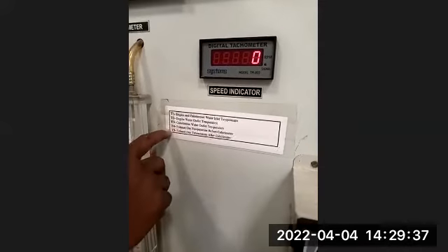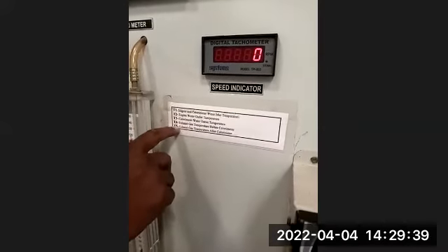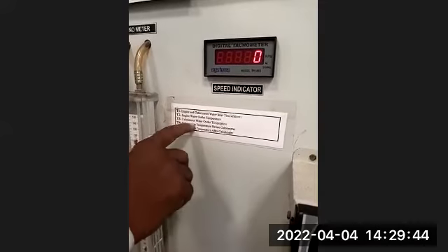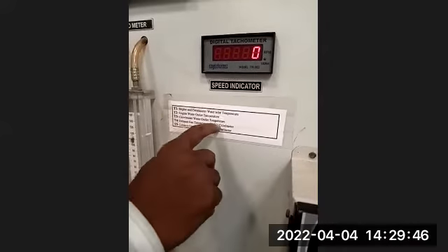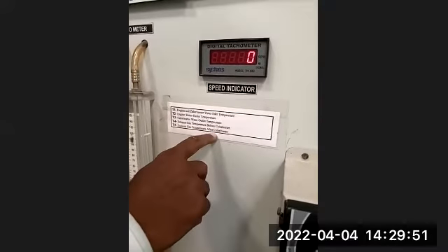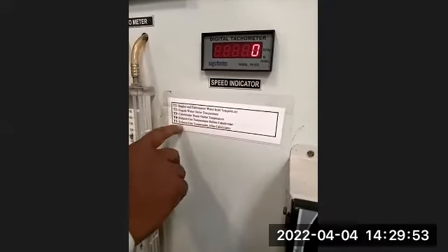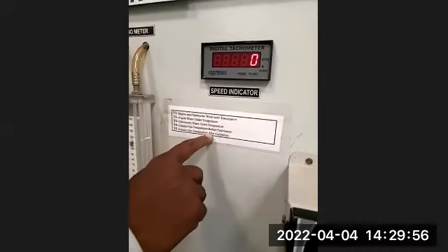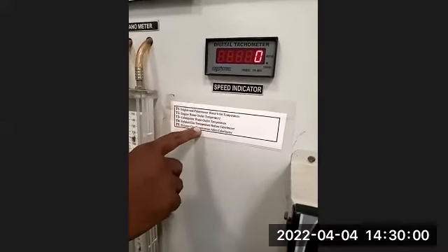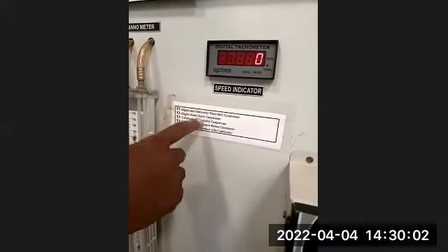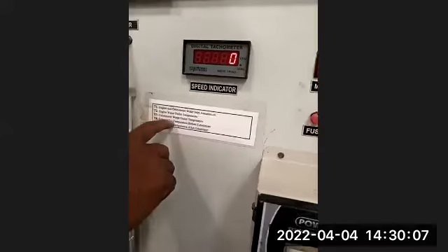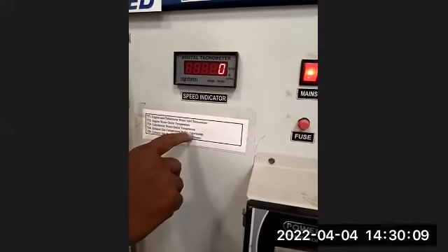Here T4 and T5 we are measuring in order to ensure that all the heat available is used. T4 is the temperature of the gas going into the calorimeter, and T5 is the temperature of the gas coming out. We want to ensure that T5 is almost equal to atmospheric conditions. When this happens, we can assume that all the heat in the gas is transferred to the water, and that will appear in the form of T3, the calorimeter water outlet temperature.